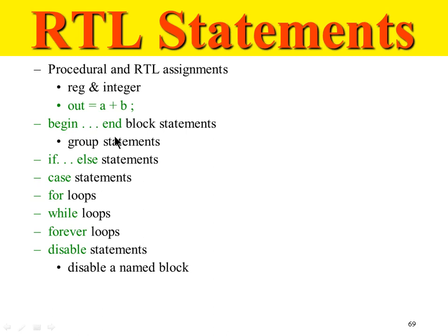Normally, begin and end is required if you have more than one statement inside the always block or more than one statement inside the initial block. It's always a good practice since you're just starting out. By default, any initial block or any always block, you should have a begin and end. So that is how you group the various statements inside the always block or the initial block.